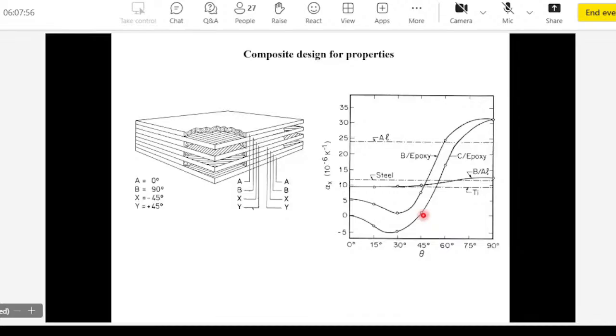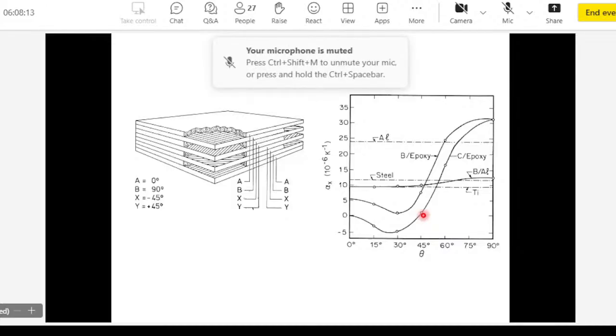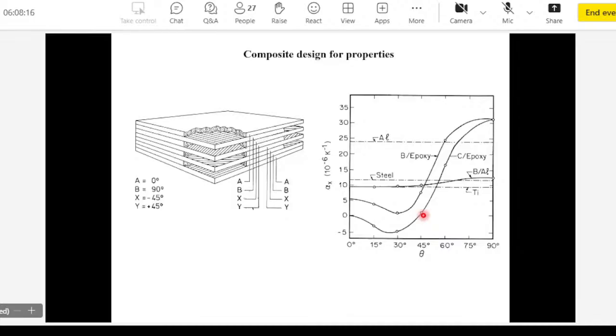And we all know the difference between strength and toughness. If you take a piece of aluminum and glass and try to scratch them with a knife, you'll be able to scratch aluminum, but you won't be able to scratch glass. But do another experiment, drop them. In one case, I'm able to scratch aluminum, but when I drop aluminum and glass, aluminum doesn't break, glass breaks. Right? So when you're trying to scratch aluminum and glass, we are looking at different properties.